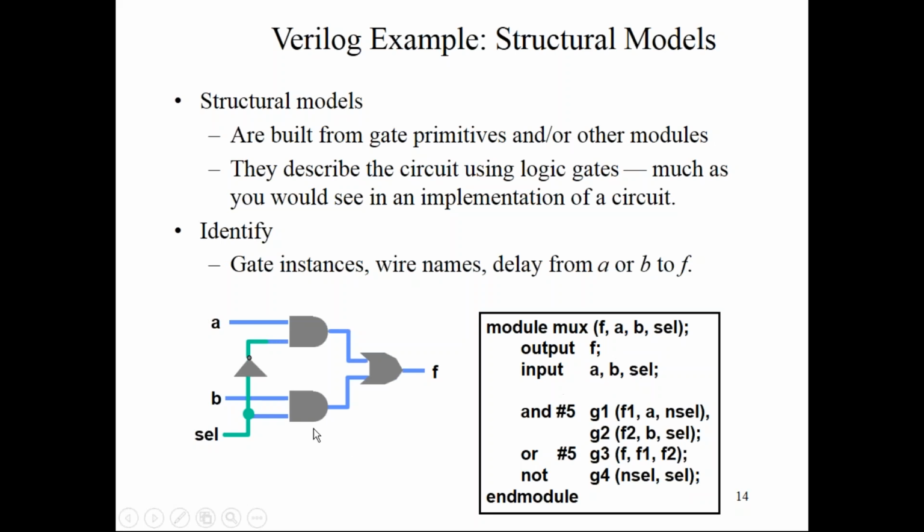So next, you are having two AND gates and one OR gate. In that, this line and this line are your internal wires, and this is also your internal wire. So you are having three wires. If you are synthesizing that model without wires, that doesn't show any warning. It will automatically interconnect.